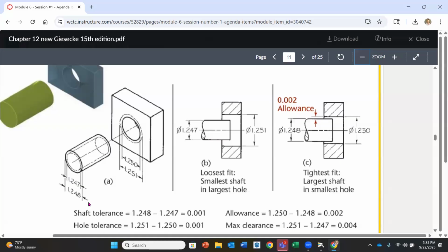But if you have plus or minus 6/1000ths on there, you can imagine that, oh, I got to add, I got to subtract, and that could be a problem. And when you're the designer, you want to eliminate as many of those types of things. So when I was at Hyson, my high-speed packaging equipment place, where we had very precise things that we were dealing with, we always had to put limits on all of our dimensions if they did not default to the title block. That way, whoever was making them, whether it was in-house or outside, they had the highest and the lowest value, and there was no question on what was acceptable.